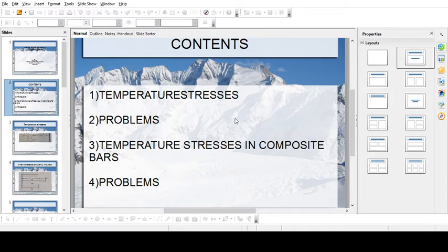Okay. So it is L alpha T minus delta, where delta is the small clearance that is given due to yield. Okay. So due to yield, that is the clearance given. Previously it was simply L alpha T. Now the strain is as usual again. Strain is equal to delta L by L. So L alpha T minus delta by L. So L and L get cancelled for the first numeric value. So it will become alpha T. And for the next one, it is simply minus delta by L.